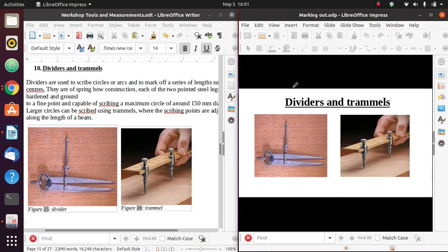I can also measure the distance between two points. For example, I want to measure my workpiece, and I don't have a ruler, but I have a divider. I'll just take my divider, open it, put it at the two respective places that I want to measure, and then transfer that to the scale, and then I can read what the distance between those two points is.